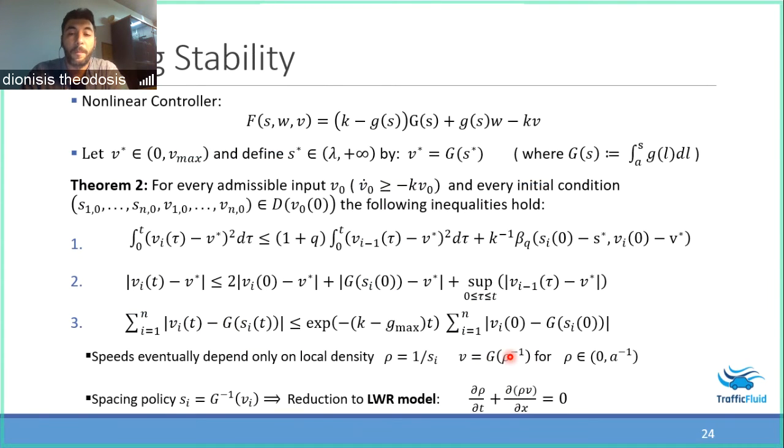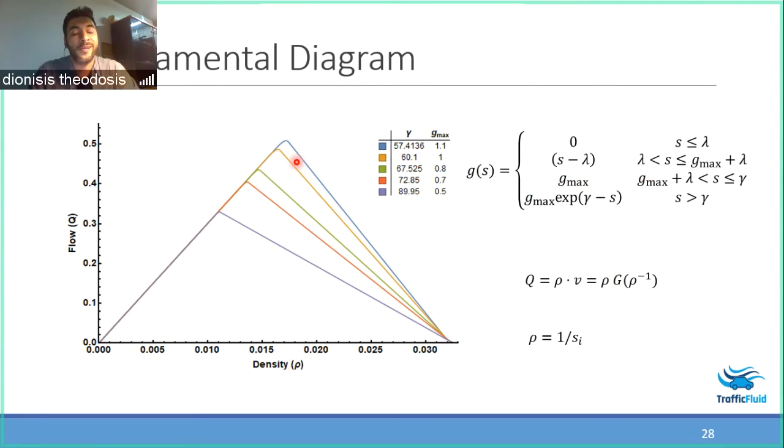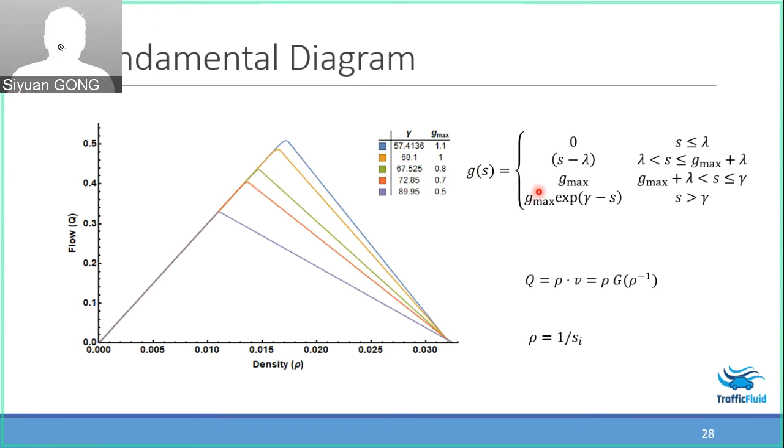Yes, but my question is that the fundamental diagram looks like a triangle, right? If we look at the congestion side, if it looks like a triangle, that means maybe the time headway is a constant value. This is because of the function g. Here, the fundamental diagram, the flow, depends on this capital G, which is the integral of this function g. If we design this g in any other way we want, we can obtain a completely different fundamental diagram, not a triangular one. This is only for this function. Okay, good. Got it. Thank you.